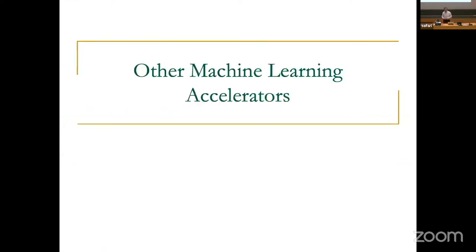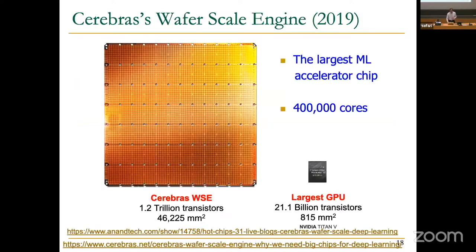So now this is systolic arrays. As I mentioned yesterday, systolic arrays are not the only machine learning accelerators. Now we're going to see the SIMD paradigm that people have been using to accelerate machine learning, because SIMD is actually a very good fit for doing convolution type parallel operations, matrix multiplication. And yesterday we saw how you can convert convolution to matrix multiplication as well, right? Remember that slide where I showed you that? You can go back to that. So basically, people have been using SIMD architectures, and this is later today.